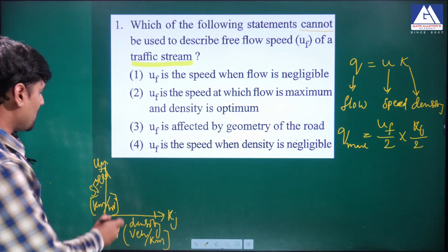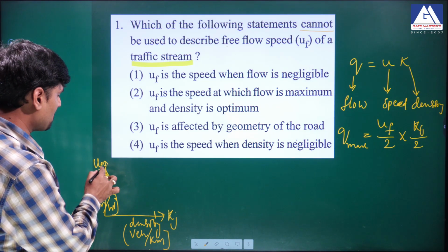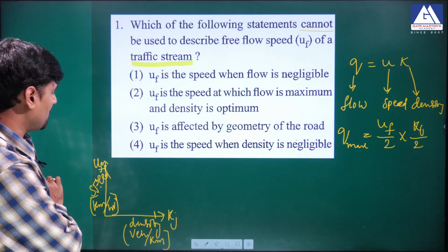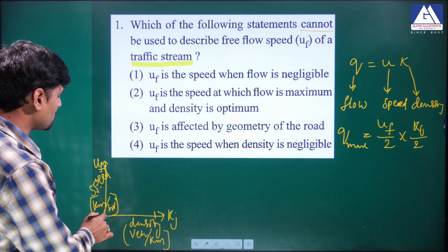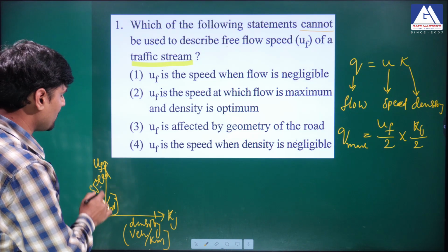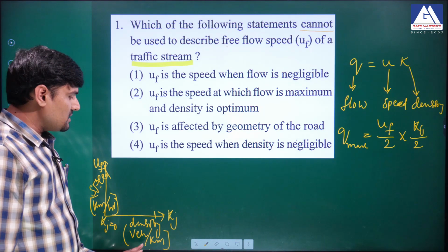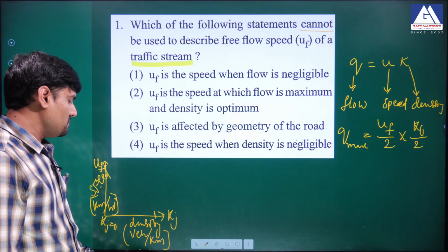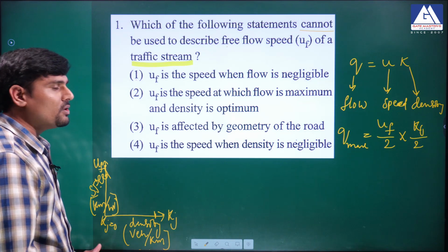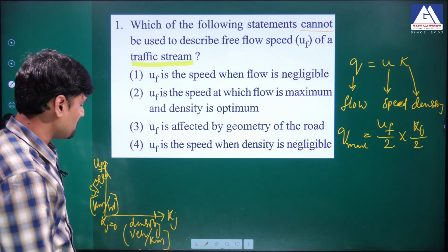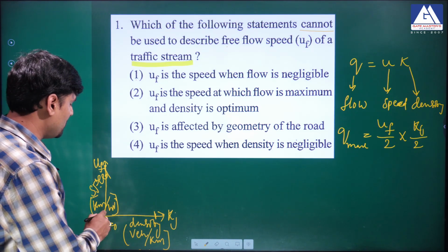So here, when the speed is free, that means free flow speed, that can happen only at midnight. That means during that time there is no vehicle present in the given section. So therefore, when the speed is so high, density is 0. And now if the density is so high, that means the extremum traffic jam condition, in such a case there will not be any movement of the vehicles. So when the jam density is higher, the speed is 0.